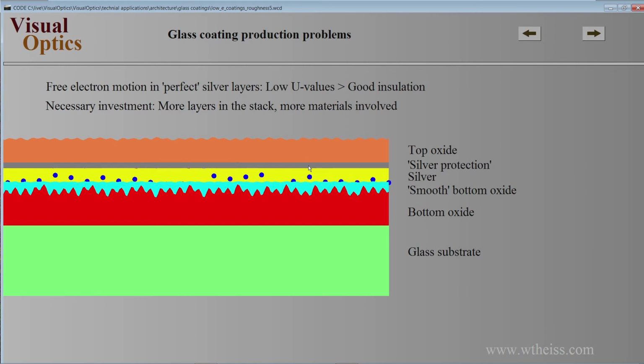Usually these thin metallic layers are very strong absorbers, so you have to make sure that they oxidize either during the coating process or immediately afterwards during the first minutes or hours of the coating lifetime. They should pick up oxygen, be ideally completely oxidized and get transparent, so they have done their job to protect the silver. Then they oxidize, and they ideally get part of the top oxide system here as transparent oxides.